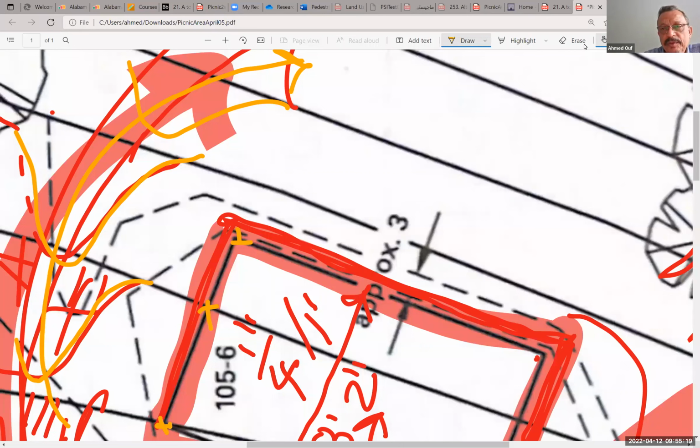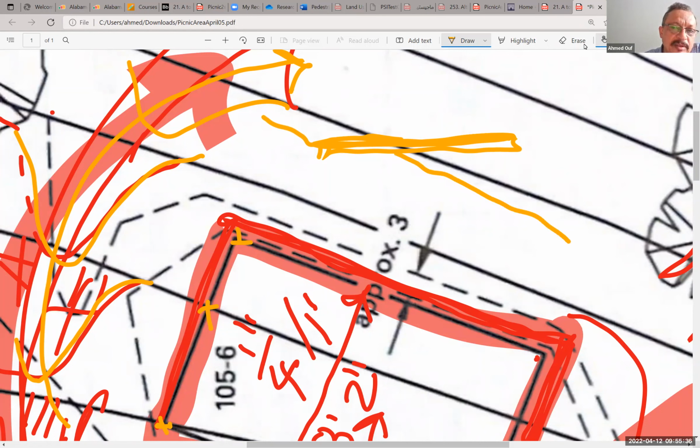If I'm drawing a section in this part, if this is our pavilion and the slope is only 1/4 of an inch for every foot here, and we are putting that on a sloped ground like this, we will have some area here to fill, and maybe nothing here to dig, or I can push it inside. So I have a dig and fill area, something like that.